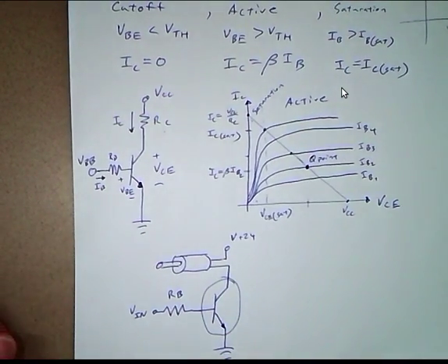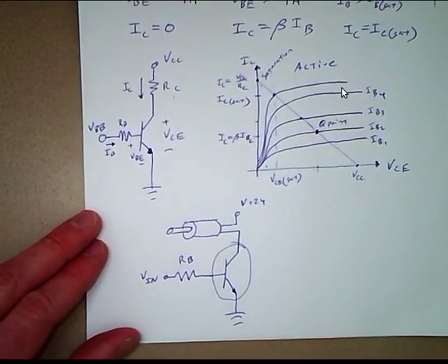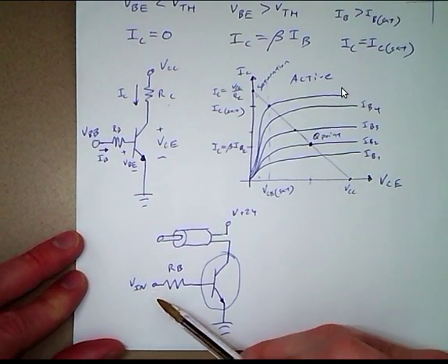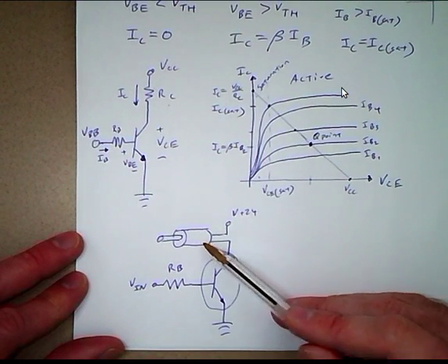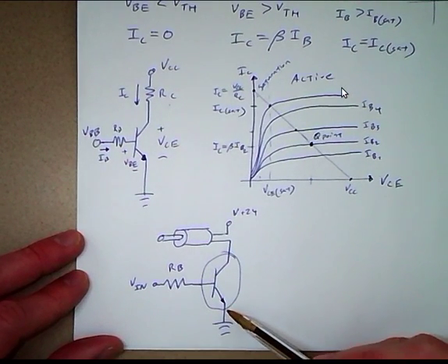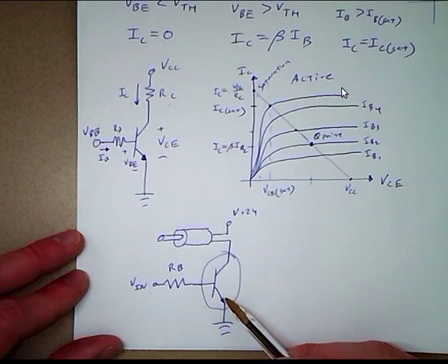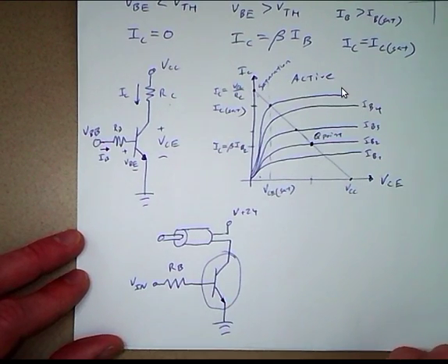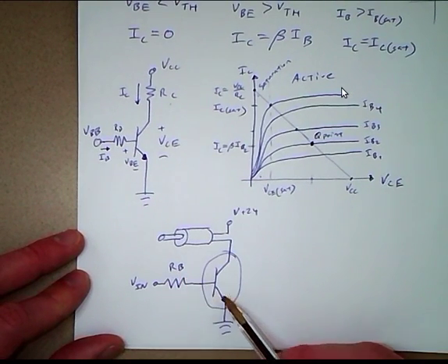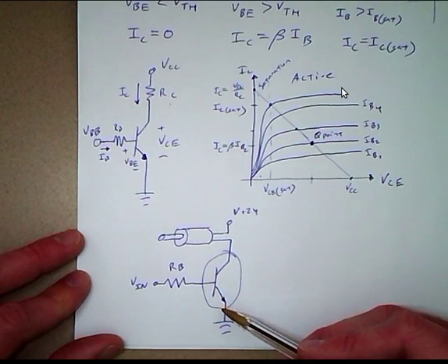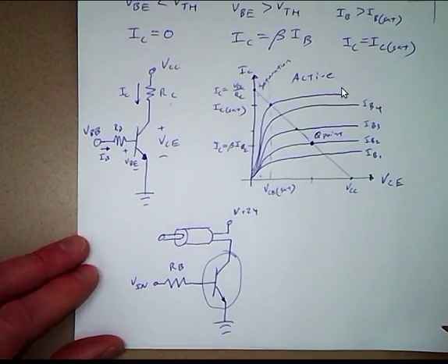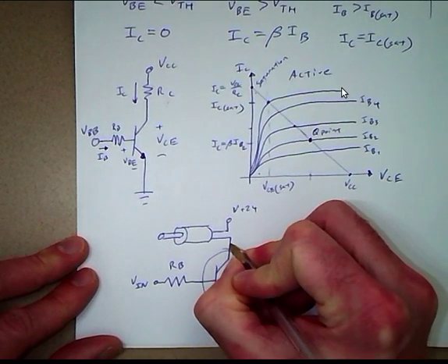Okay, so we have a solenoid that we want to turn on and off with a microcontroller, say. And the microcontroller doesn't supply enough current, or doesn't have the right voltage to control this solenoid. So we could use a transistor as a switch. And in that case we want it to be in saturation. So we need to figure out what value for RB we want in order to be sure that the transistor is in saturation. And one thing is missing from this that'll protect the circuit.